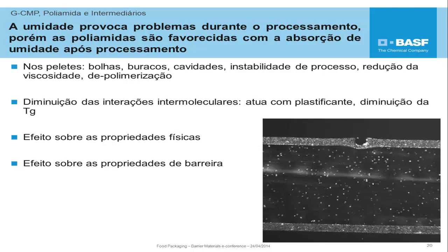Why does this happen? It happens because the water or humidity takes position between the structures of the molecules, becoming a natural plasticizer for the polyamide film, diminishing the interaction and contact between the structures of the molecules of the polymer, also decreasing the Tg or glass transition point. The plasticizing effect results in softening and reduced rigidity of the material at lower temperatures.